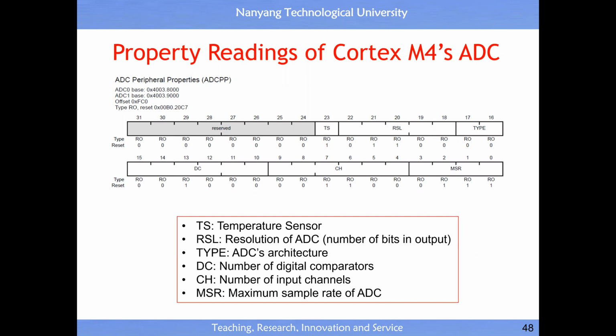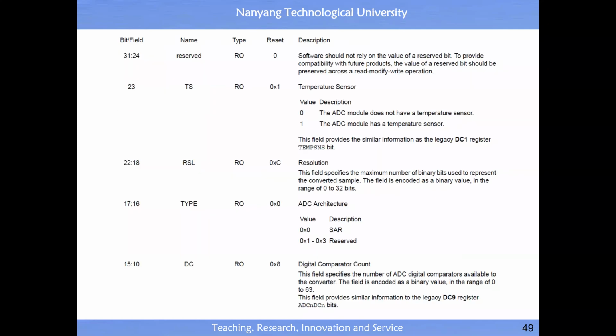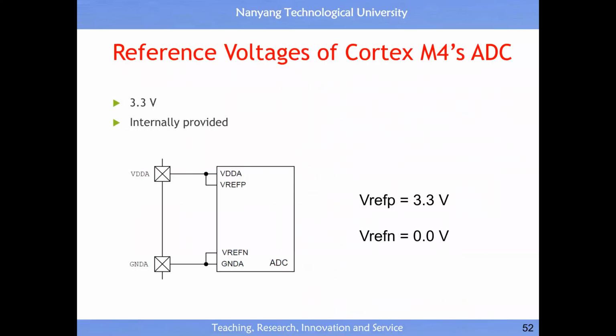Then if you buy a second-hand Cortex microcontroller, you need to do this verification. You may get a second-hand microcontroller with reduced capability. Okay, this is just something for you to know. All right, if you buy a second-hand car, this car may be a modified version, not the standard car. By default, you have 12 inputs, you have a sampling device, you have 2 quantization devices, all right. But you may purchase a second-hand one with reduced capability, all right, so you can use that register to verify.